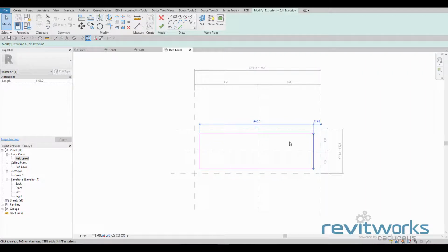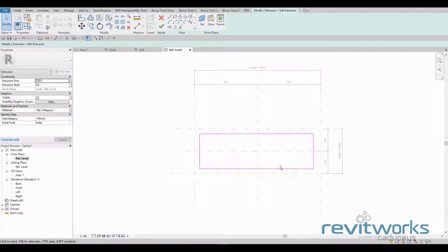And it's worthwhile knowing that Revit does this, so you don't need to padlock the pink lines all the time. Typically, if you're tracing a pink line over a reference plane, it's going to stick to it. So it's only when you get complex on your families and you might need to differentiate which reference plane that pink line should be sticking to, do you really need to padlock those pink lines. If in doubt, you can. So don't forget, align and lock also works. So if you want to be absolutely sure, you can align, lock, and padlock. And actually, that's a good way of fixing up things that somehow get broken on more complex families.